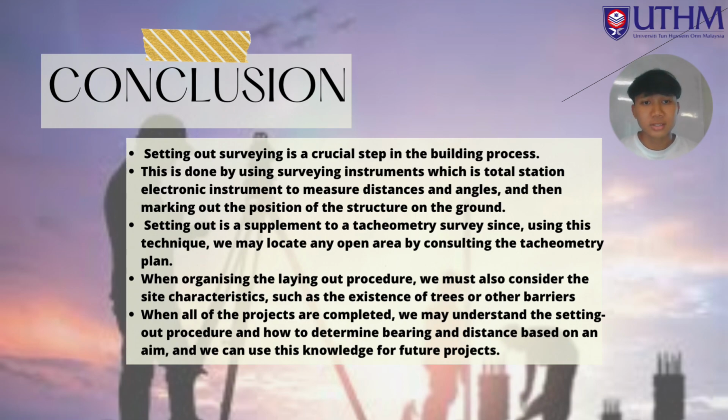Setting out surveying is a crucial step in the building process. This is done by using a surveying instrument, which is the total station, to measure distance and angle and then mark out the position of the structure on the ground. After calculating the distance, we use tape to measure every distance from point to point.